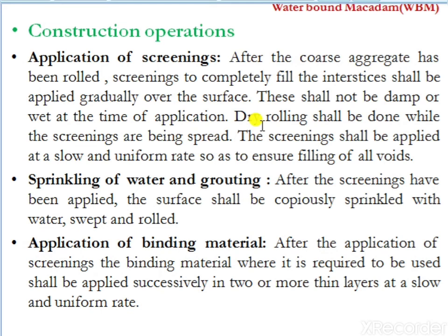So after this, the next step is application of binding material. After the application of screening, the binding material, where it is required to be used, shall be applied successively in two or more thin layers at a slow and uniform rate.